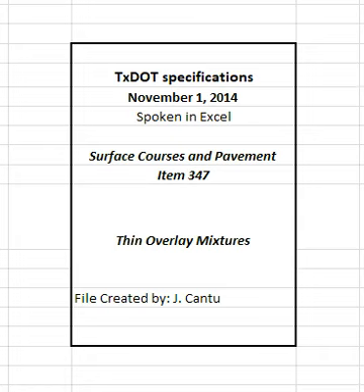The engineer will have the option to perform the following tests on the trial batch. Tex-226-F, to verify that the indirect tensile strength meets the requirement shown in Table 8, and Tex-530-C, to retain and use for comparison purposes during production.